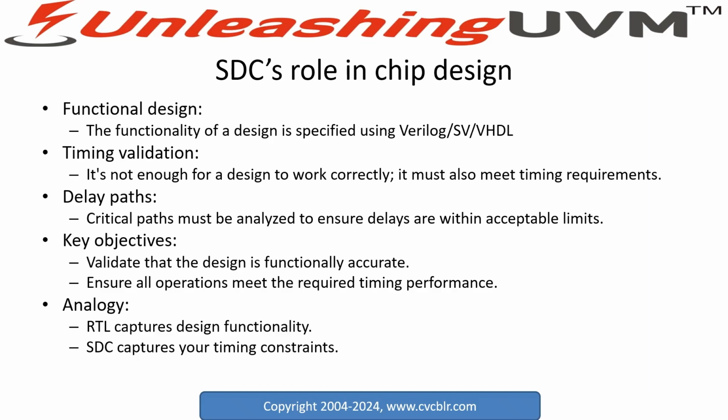We're going to talk about abstraction level timing, wherein, for example, set input delay, set output delay, set max delay, certain things that if you want to verify, how do you verify? But more importantly, from an SDC perspective, what are the false paths? What are the multi-cycle paths? What are the timing exceptions that you want to verify? Because these are abstraction level, and you could actually verify a lot of that at RTL level.